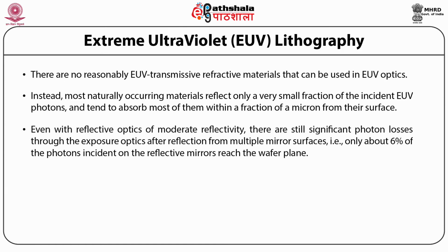So even with reflective optics of moderate reflectivity, there are still significant photons lost through the exposure optics after the reflection from multiple mirror surfaces. That is, only about 6% of the photons incident on the reflective mirrors reach the wafer plane.